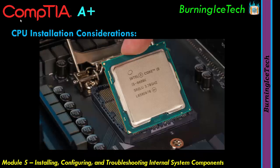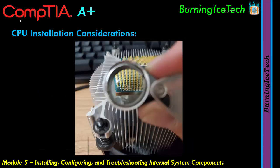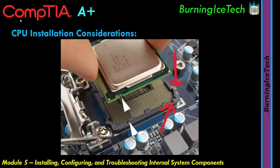If you hover it over the slot, you can see the correct way to put it in. You'll find on the edge of the CPU, it's got little holes in it. That's going to align with small little pieces of plastic sticking out on the sides of that slot where it needs to slide into. It can only go in one way. You'll also notice on the bottom of the CPU there's a pin missing. Sometimes 3 pins missing, but there's normally at least 1 pin missing on the bottom of that CPU. And if you check on the motherboard, you'll also see 1 contact point that's clearly missing. That also tells you which way it needs to go.